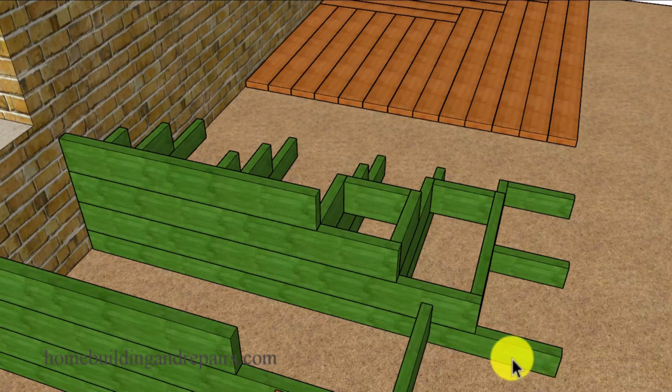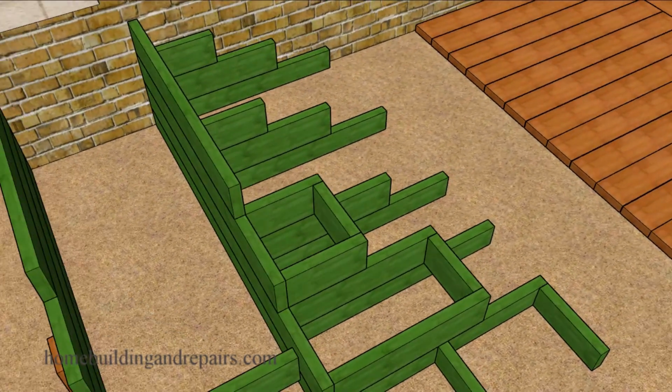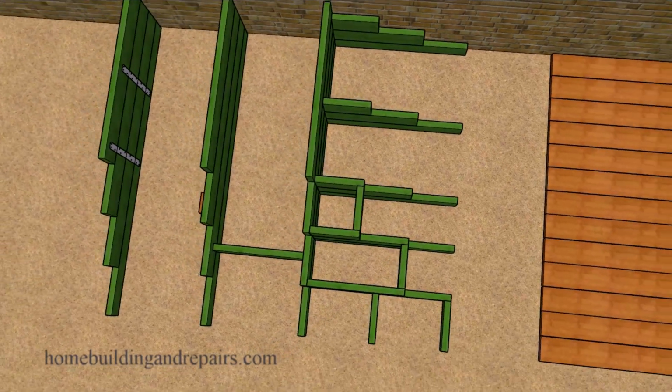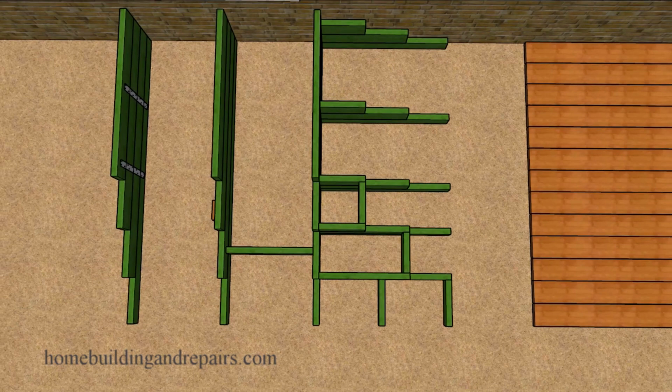So again, these lower boards, all of them are going to be 1.5 inches shorter if we're using 1.5 inch decking. If I'm using 2-inch thick decking, then I'm going to subtract 2 inches off of my 2x6. And I won't be going into a lot of detail about that in this video. However, I do have plenty of other videos at our website. Make sure you check them out if that doesn't make sense.